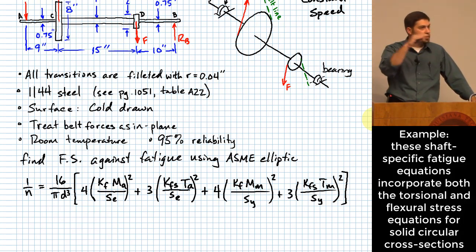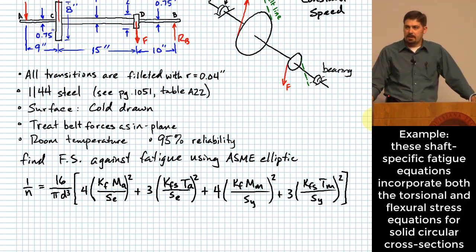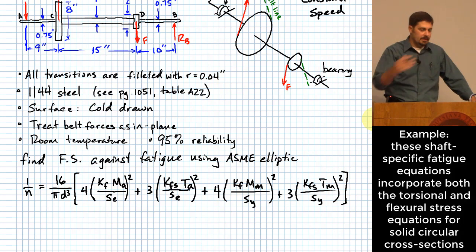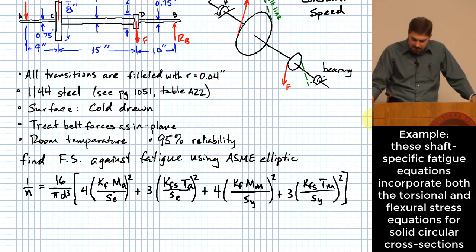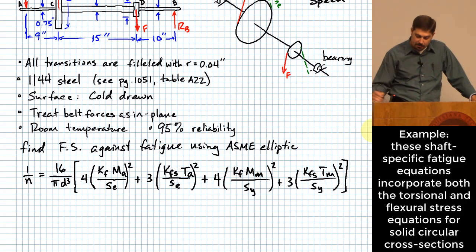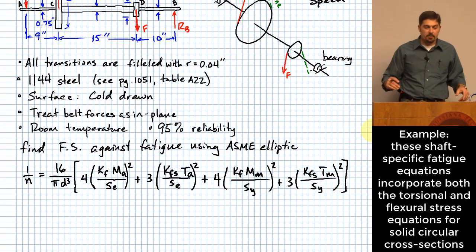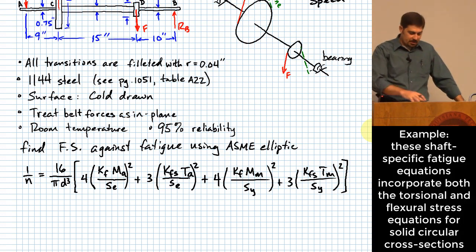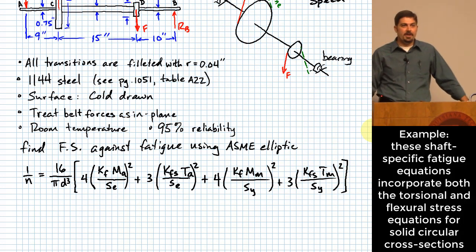It gives you a smooth, continuous criterion so you don't have to do two separate things to evaluate first cycle yielding as well as the fatigue stuff. It doesn't do it perfectly, as in it is not conservative. You could end up in a particular position on the failure locus where this method would not predict failure, where you would in theory predict first cycle yielding.